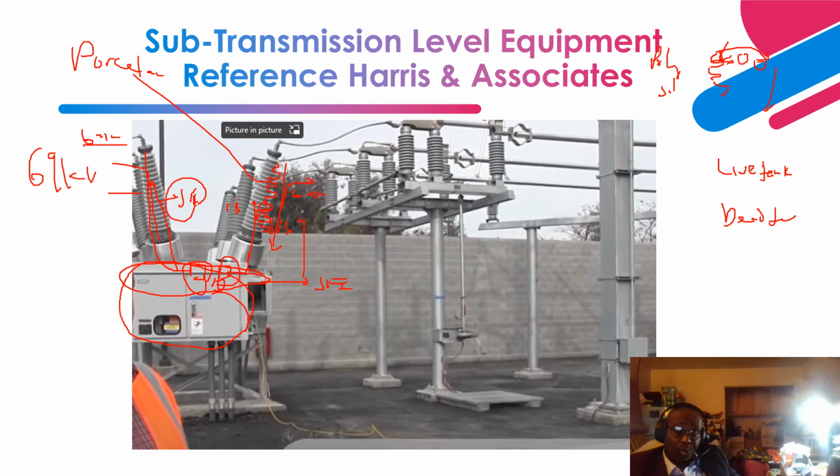And I also explained to you the disadvantages. Because it is flexible in nature, it can basically break easily if birds with long beaks poke on it, right? And the great advantage of porcelain is its mechanical strength. But if somebody hits it with a stone, then it's going to break and shatter, and elements of the water can get into the insulated medium and degrade it. Okay, so that is the difference.